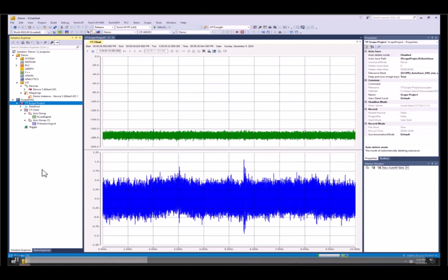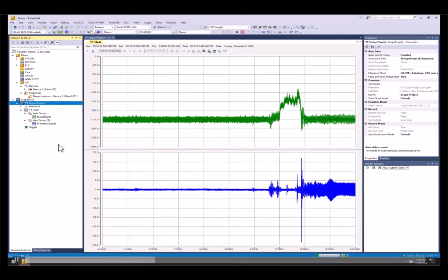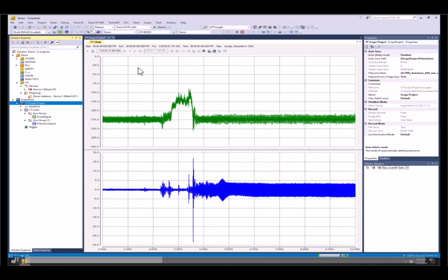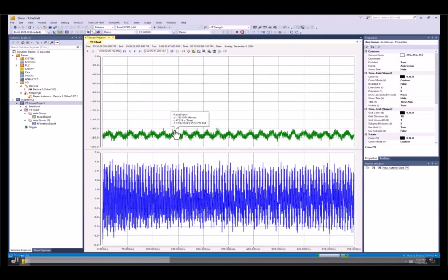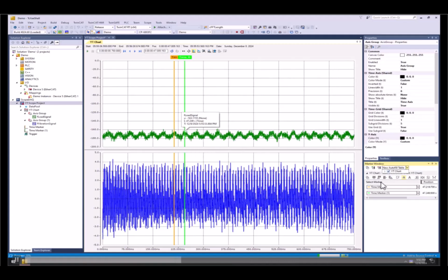And so I'll resume our scope measurement, and I'm going to go ahead and induce a disturbance or an imbalanced load. In this case, it's simply just in the form of a fan. And so I want to go in here and add a couple time markers and identify what the fundamental frequency is of this load as I'm running it at the lowest speed, I'll say.